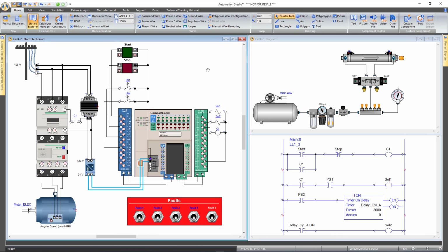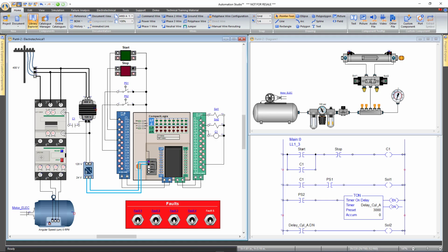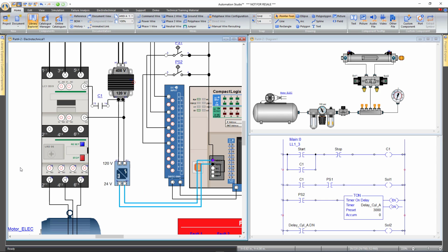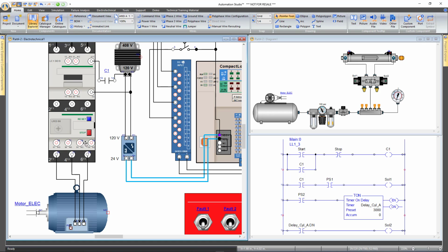The last one I want to do is actually take this compressor and jam the motor, jam the pump. So if this is jammed, because of a mechanical link between the two, the motor should jam as well, which will make the current increase and then my overload trip. But in order to make my overload stop the circuit, I need to actually use a normally closed contact of this overload, which I'm not using at this point. So I'm just going to bypass here and go through my normally closed contact of my overload, like this.